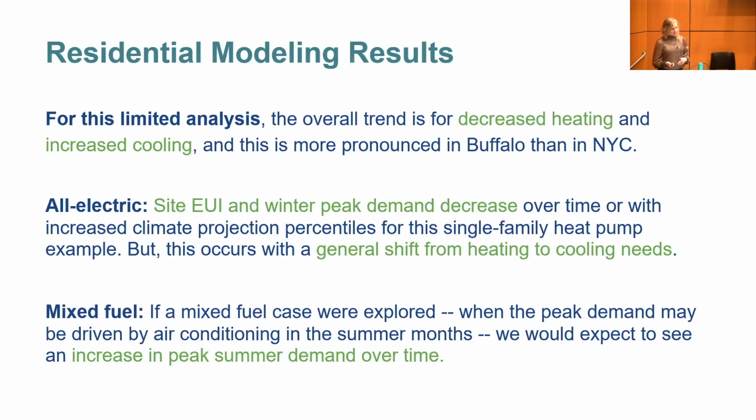For this limited analysis, this was a single example of a residential building in New York. We saw decreased heating and increased cooling, and it was more pronounced in Buffalo than New York City. This is an all-electric example, so we saw a winter peak and a general shift from heating into cooling. If we looked at a mixed fuel example, where the peak demand might be driven by air conditioning, in that case we would probably see an increase in peak demand over time, assuming that the peak is still happening in the summer, which in New York, it might not be.